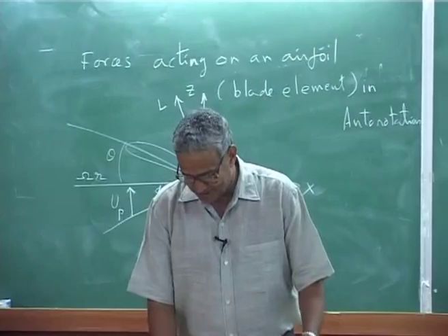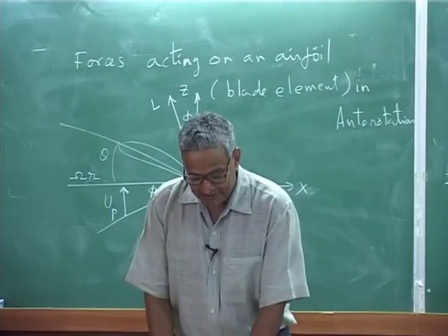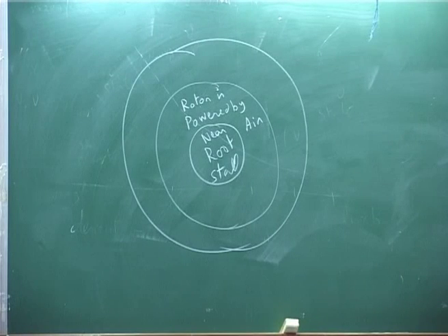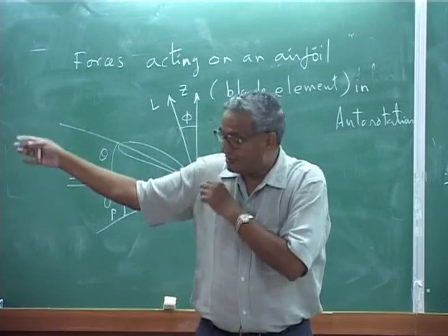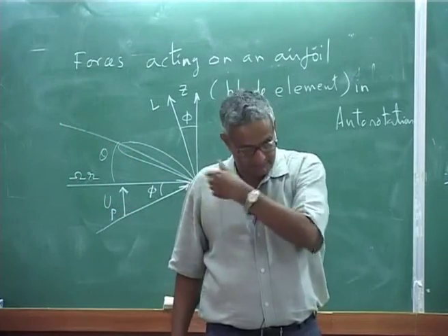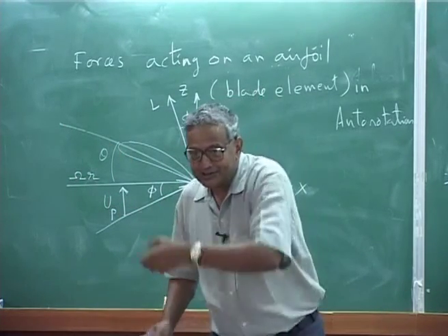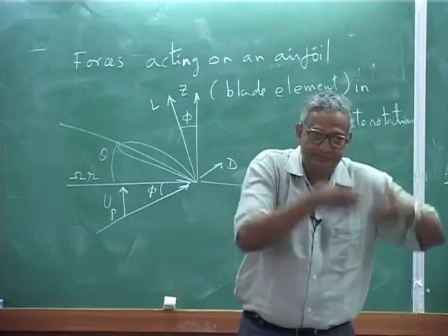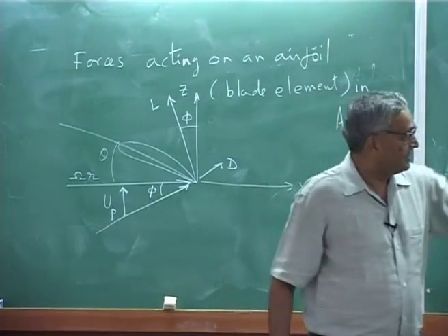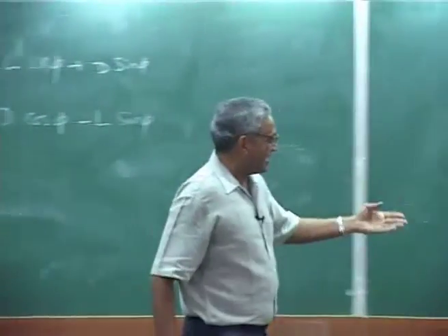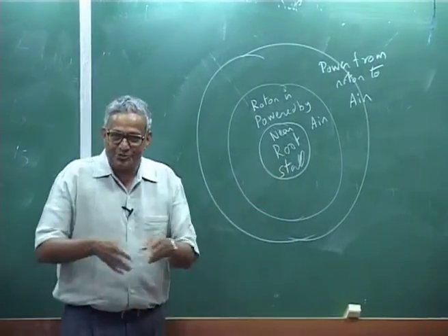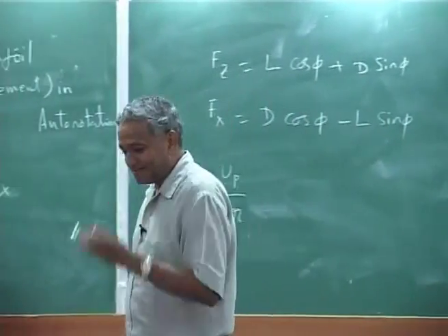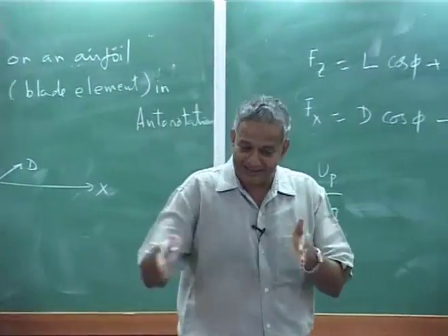Now, you see, in auto rotation, it is essentially the integrated effect. That means, in the outer region I am actually dragging the rotor, that means I am wasting power. In the inner region, the air is pulling the rotor. Further inside, it is stalling. That is why near the root it stalls. Even though it stalls, you know that root cut out, every region is there. So, you say okay, I neglect it, it does not create much lift or anything like that. That is the reason.